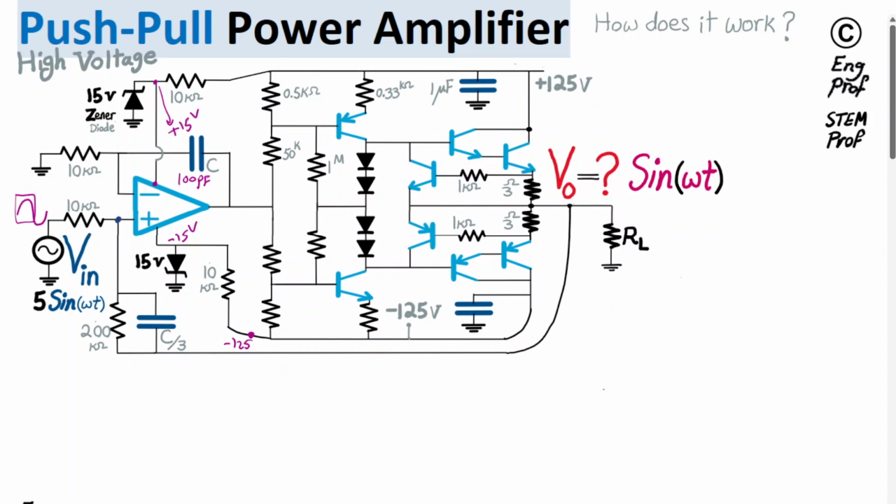As the op-amp tries to increase the output voltage, this transistor that is on the verge of operation is turning off, because with the voltage at the base increasing, it will shut down this transistor. And then the PNP transistor turns off, and the NPN transistor actually starts having more current. So this current source starts becoming more active.